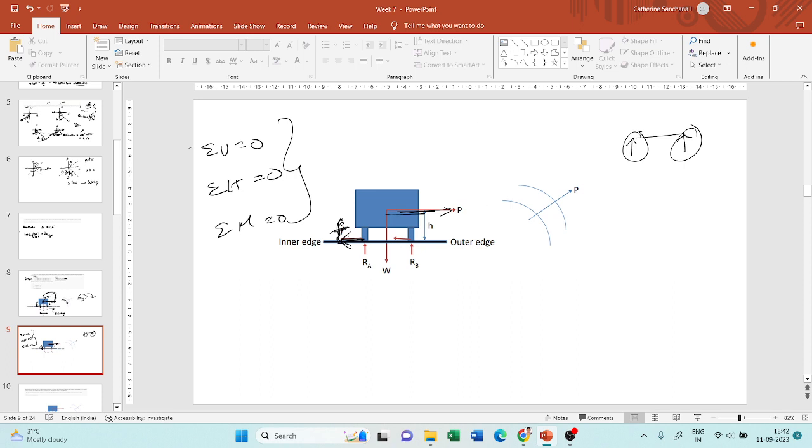So as we saw, skidding is caused by the pulling out of the vehicle by the centrifugal force. This is a horizontal force, right? And this has to be balanced by the frictional force, which is exerted between the tire and the pavement. So this comes under the topic of summation of horizontal forces is 0.